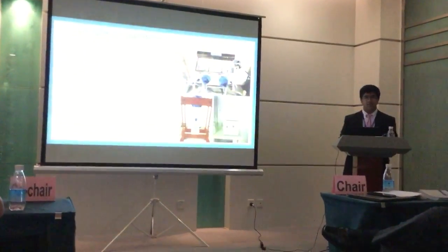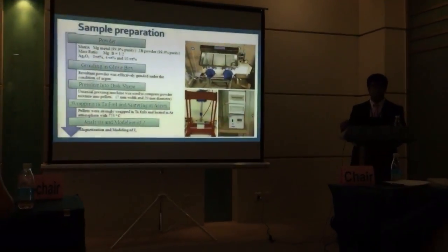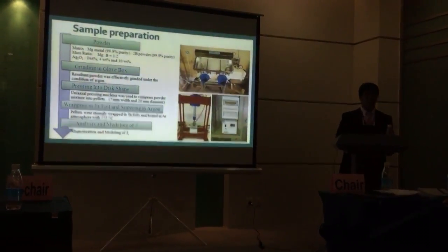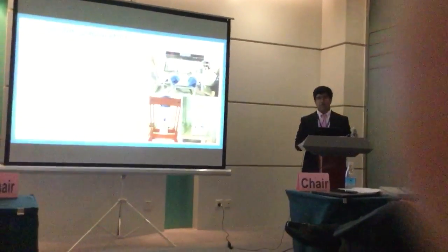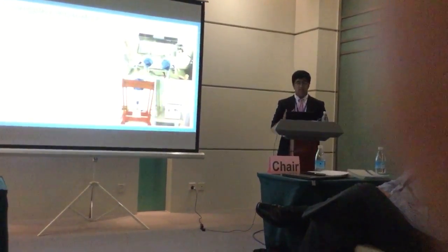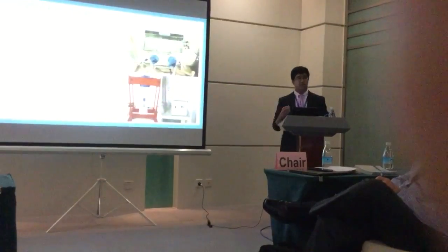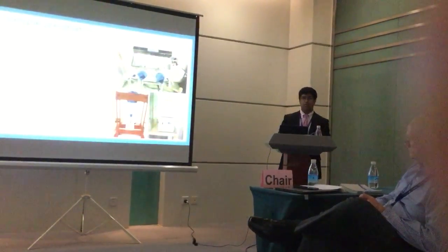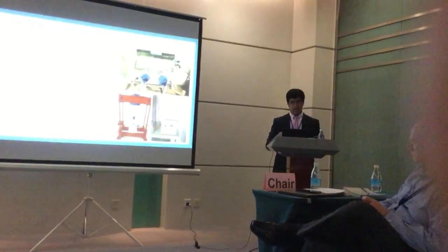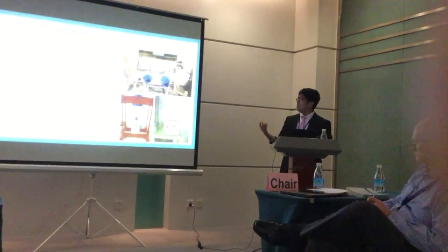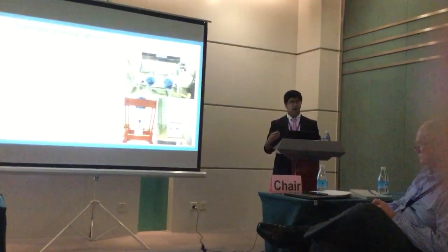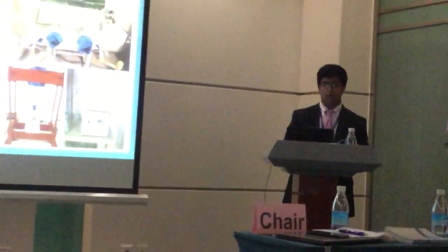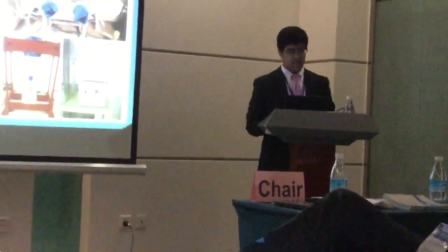So now I'd like to briefly discuss how I prepared a sample of bulk MgB2. The first process that was utilized is the powder preparation. In order to make the powder, I needed the Mg metal and the B material, which are both 99.9% pure, and the molar ratio to produce it was 1:2. In this MgB2 sample, I had also varied the contents of silver, and the varied contents were 0%, 4%, and 10% in weight.